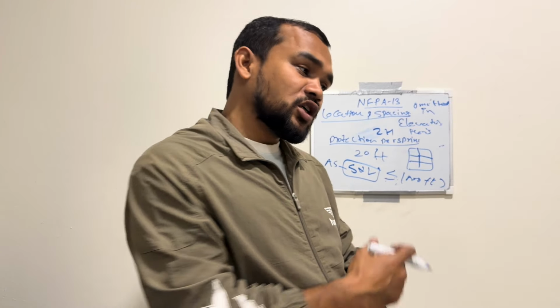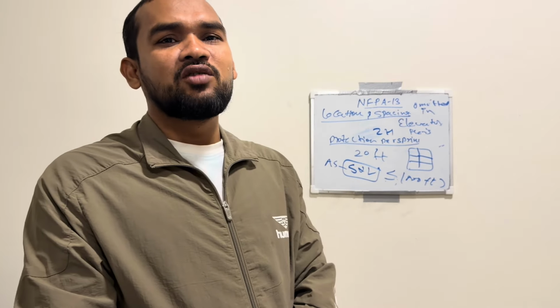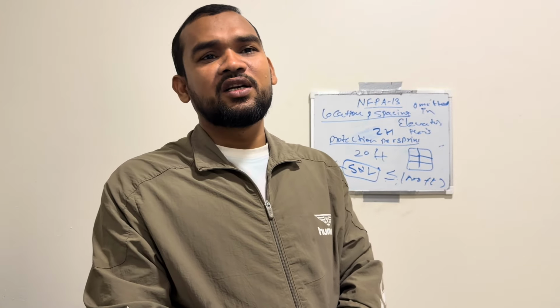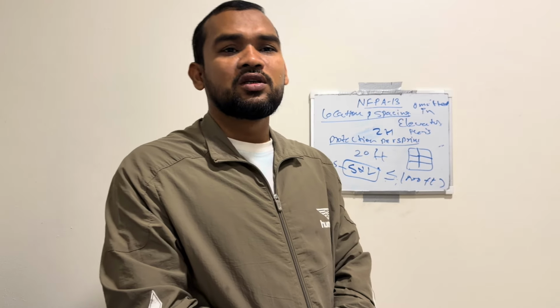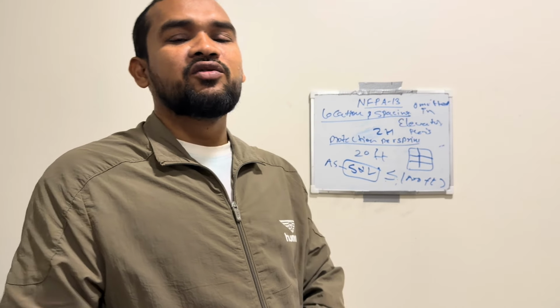And for the sidewall it should be 196 square feet. Spacing for sidewall, maximum distance between sidewalls is as per the table in chapter number 10. The minimum from the end wall is greater than or equal to 4 inch. Under overrated door for ordinary hazard, light hazard spacing rules are allowed for this.